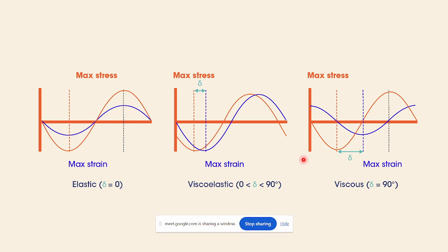And here for your information, I should add another point. For example, if you are using natural rubber without any filler, in that case the viscous part will be higher. But when you are incorporating filler continuously, the elastic part will increase with the addition of the filler amount, and based on that you will get different results, because the elastic component is increasing with the addition of the filler. So from viscous you are moving towards viscoelastic to elastic.